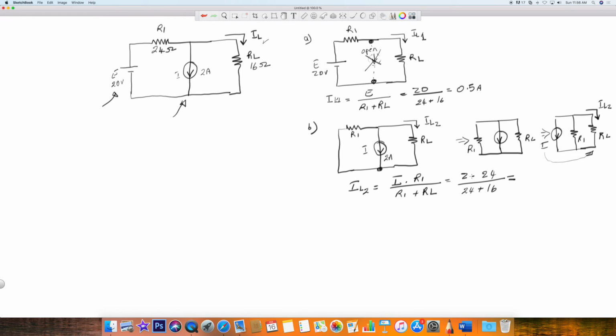in our case here, the current is really going the other way. So watch how this current is going this way versus my starting point. So we know the two partial currents are going to go this way. So this is important. So what I have here is really a minus. So just make sure you see that minus in there, because this current here is opposite to IL2. So this is your IL or your minus IL2. So this is going to give me minus 1.2 amp.